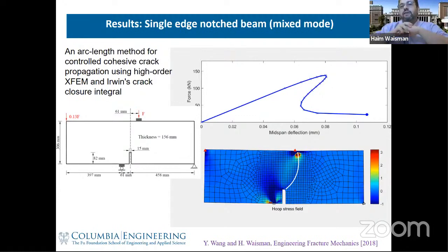But the solution itself is formalized in a semi-infinite domain, right? So you assume a very far stress field, and that's how they derive it. So that's why in all XFEM problems, it doesn't really matter. You are just taking what is happening at the crack tip itself. It doesn't matter what happens far away on the boundary conditions.